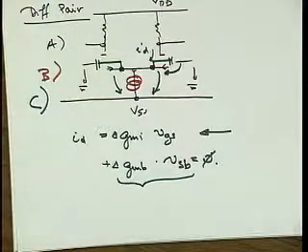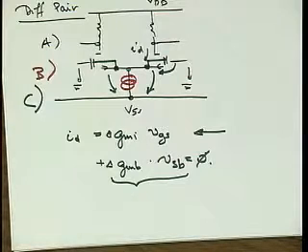Solution B, well, if we are content with a medium range common mode rejection ratio. If we want to have really excellent common mode rejection ratio, 100 dB or maybe even a little bit more, then we need solution C, where we are tying the bulk and the source together.